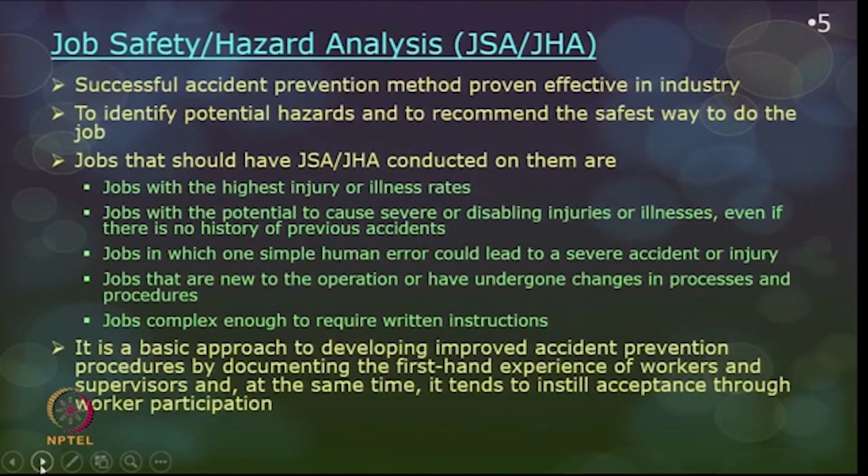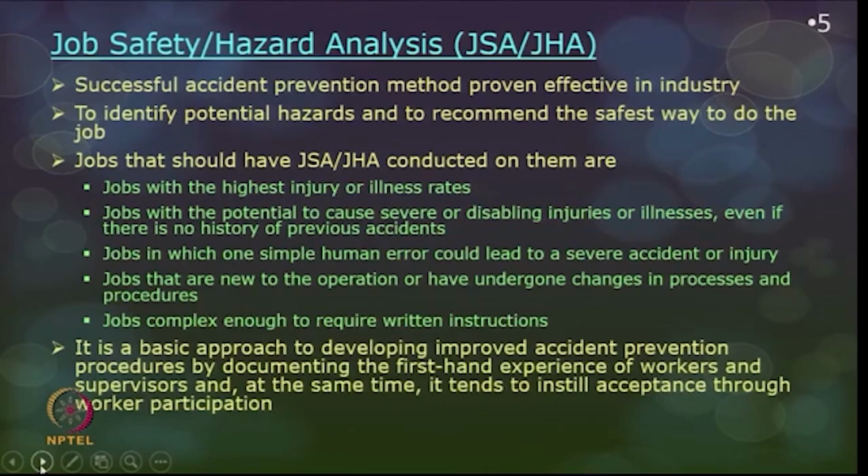Once you have thoroughly done that mapping and the phase analysis is partially clear, you may have to do the job safety analysis or job hazard analysis. Both are almost the same. One is identifying the hazards, another is safety analysis. So in a way you are identifying the hazard and you want to provide a situation of complete safety in each construction operation. In short form it is referred to as JSA, job safety analysis, or JHA, job hazard analysis.